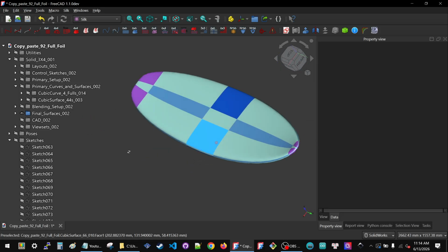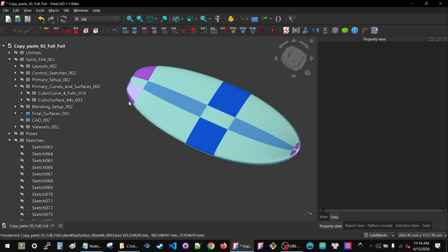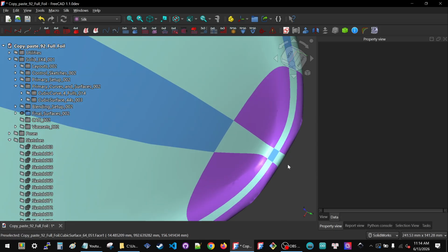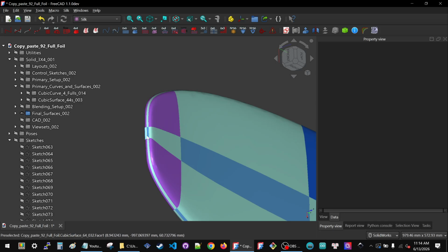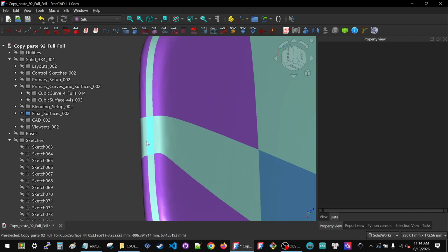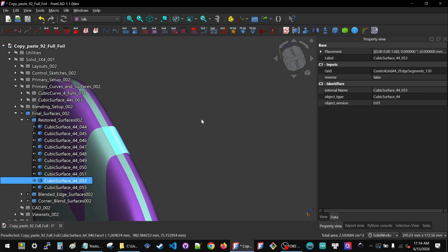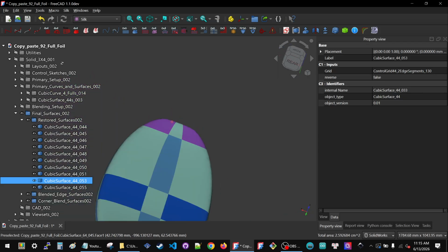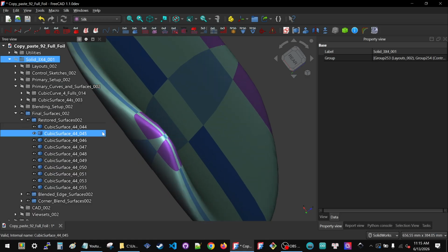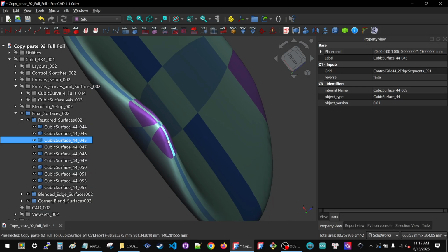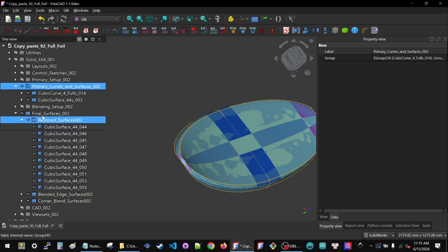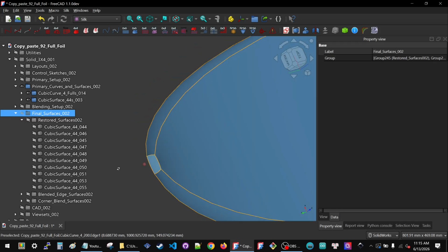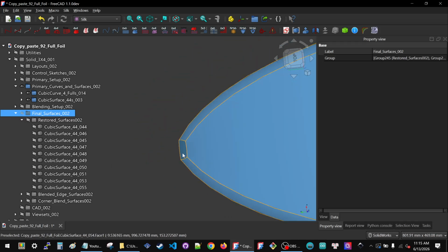What else do we need to do before we do the next level blending, which eliminates the defects and is just super cool? Well, right now this front face is completely flat, and the tail is completely flat. The tail being completely flat is fine. We can call it an intentional feature that there's just a little spot on the back end that's exactly flat. But at the tip, because we're trying to make a pointy nose, we should give the primary surface some curvature.